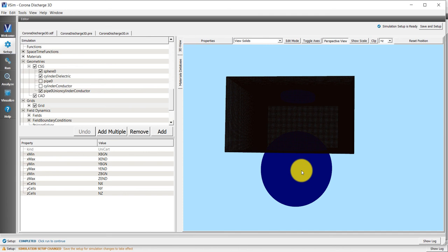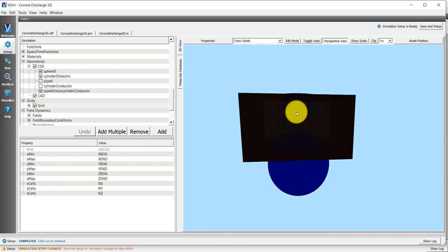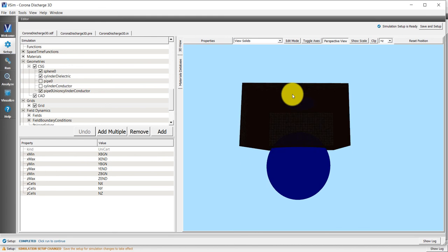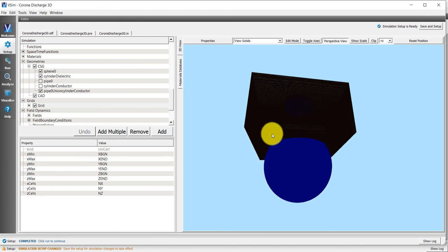For one thing, I don't need this whole sphere. I only needed the top part of the sphere. So that saved me in computational time. And so the boundary conditions on the lower y and on this sphere are identical. They're both 0 volts. They have to be physically. They are touching. So two conductors that touch will be at the same potential.